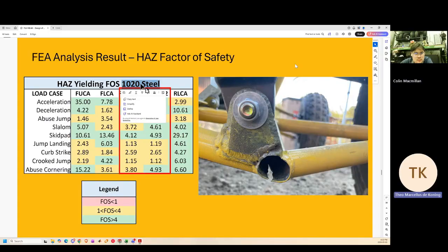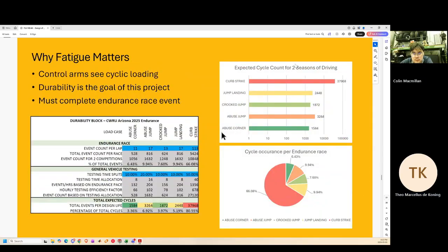We were advised by Professor Gooch to just assume that it's mild steel because, from what I understood, you can't get any weaker than this. Oh, really? So if you weld with 1020 and then you have heat affected zones, the heat affected zones would also be as fragile as 1020. That's kind of what I think. Okay, so that's good. We are good against static analysis.